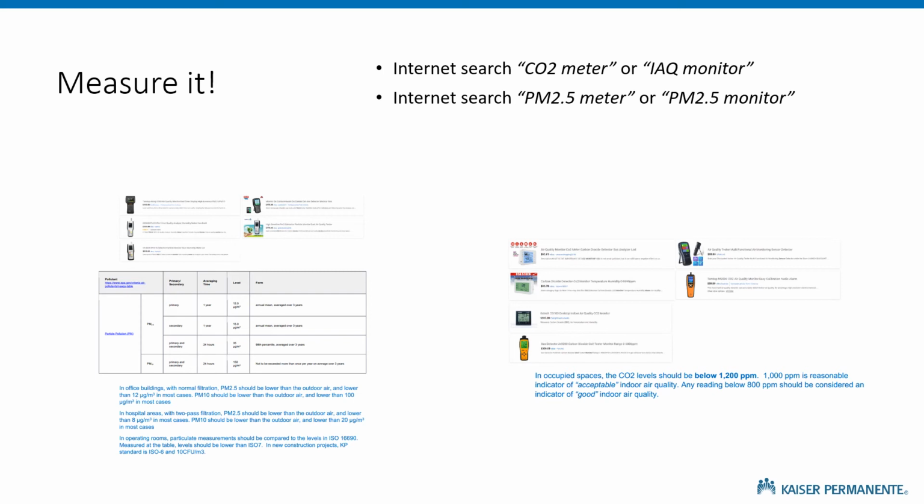There are some readily available products that measure PM 10 and PM 2.5 and PM 1 along with VOCs and formaldehyde for about $250, maybe $300. If you want to get a full-blown banded particle counter to read 0.3 microns and 2.5 and 10 microns, those are about $1,000. The one that our guys have is about $800. And then the really full-blown 6-band particle counter costs $1,500, $2,500. But you're really not going to need that unless you're certifying clean rooms.